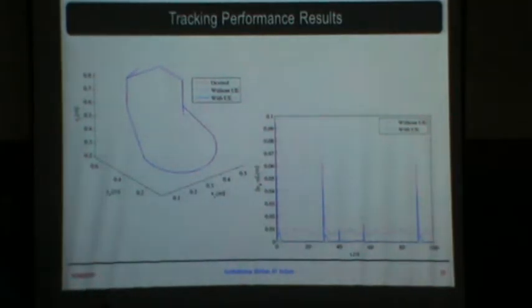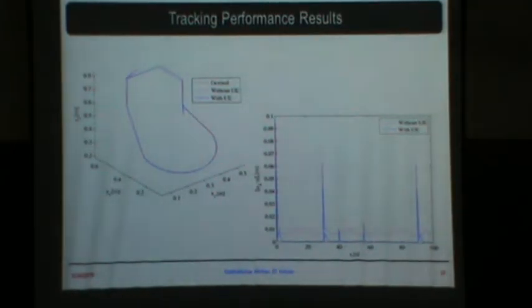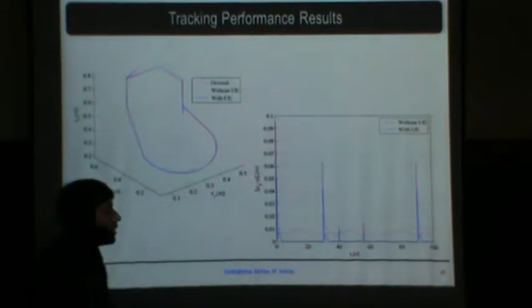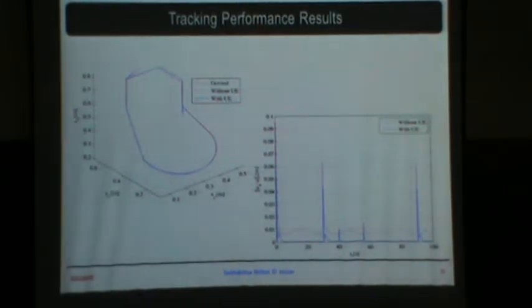Because while you are picking and dropping, you cannot anticipate, because you don't know what the payload is. Here we have taken a 5 kg payload. Even if you close your eyes and are suddenly given a bottle, your arm also will go down unknowingly. But if you know that you are picking a bottle, you will prepare yourself and pick it. That's why these errors are there. Otherwise you can see that the error is very close to 0.